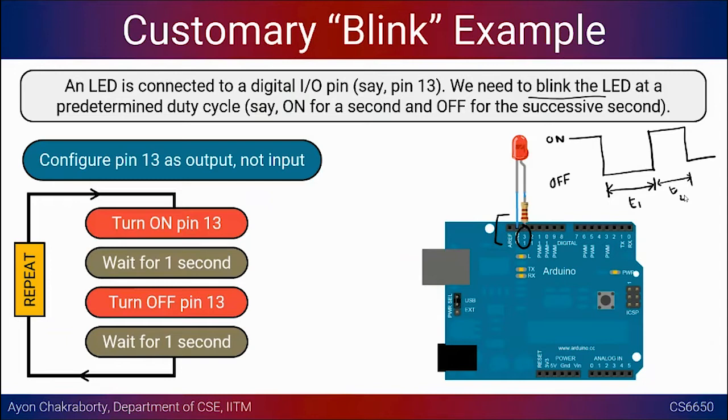So these are the two different times. In this case, we have taken both of them as 1 second. So we have to turn on that pin number 13, wait for a second, then turn off that pin number 13, and then again wait for a second, and this is going to continue, right?